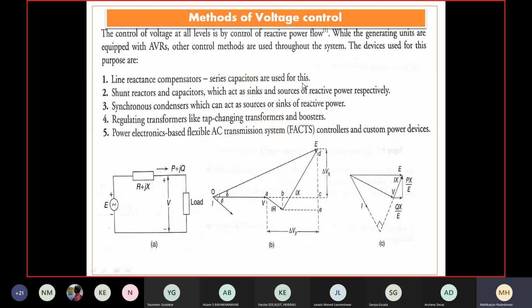If you understand the single phase RLC series circuit concept, XL and XC are opposite to each other in vectorial representation. Suitable compensation of XL can be done with XC to cancel that reactive side. If the reactive side cancels off, the resulting angle phi becomes very narrow towards 0. So cosine 0 goes to 1, and the power factor simply becomes 1 at that time.